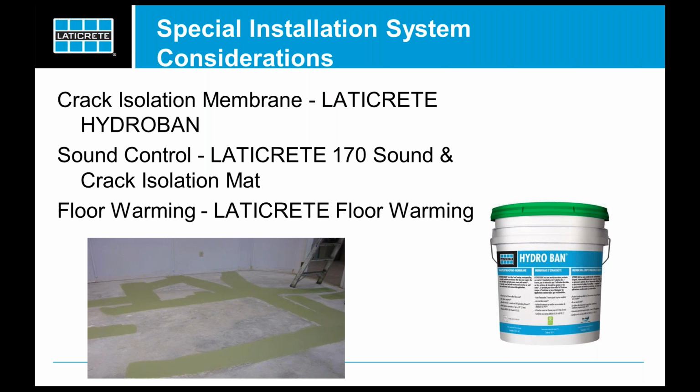So Laticrete has a product for every one of these special considerations. And in some cases, you even have combination membranes, like our Hydraband that we see depicted there, which is both waterproof and also acts as a crack isolation membrane. So you get a multifunctional membrane to be used in some of these applications. So again, the sequence is always prepare your floors first, or prepare your walls first, get them nice and level and smooth, and then you follow that with the required accessory, a membrane, sound control, or floor warming.